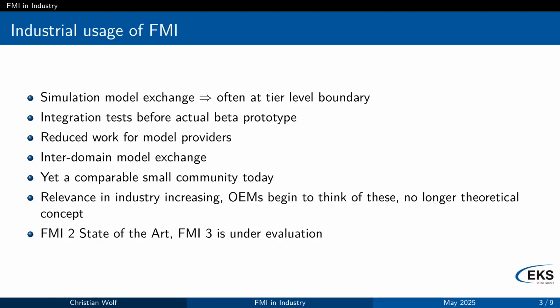And you have to say that at the moment FMI 2 is state of the art, meaning that if an OEM asks for an FMU, then it will be FMI 2. FMI 3 is under evaluation, but there is no breaking feature out there that the OEMs at the moment say, okay, we need FMI 3. This can change depending on the use cases of the big players.